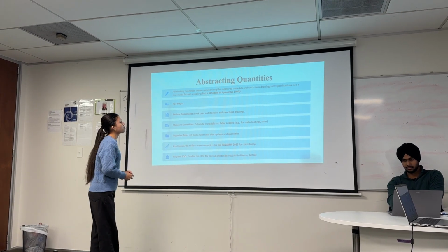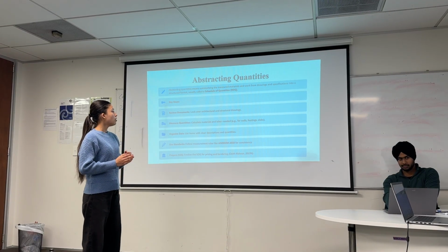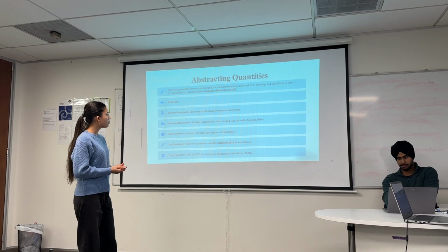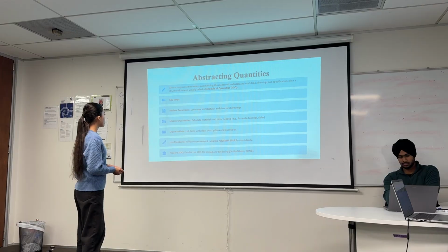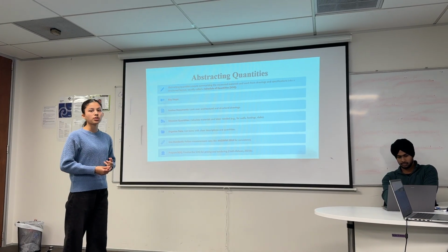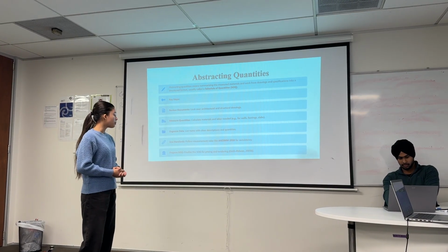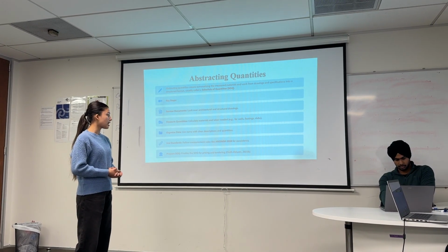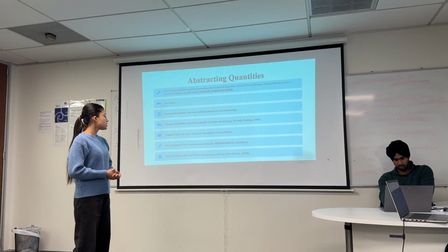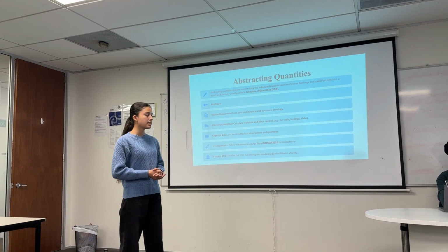Second one is measure quantities, calculate materials and labor needs like walls, footings, slabs, and organize data. List items with clear descriptions and quantities. Use standards. Follow measurement rules like ANZ SMM 2018 for consistency. Prepare SOQ. Finalize the SOQ for pricing and tendering.